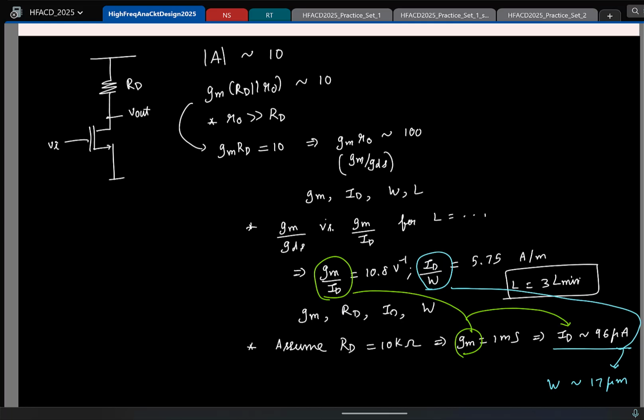Like even the question from the previous example, where we plotted gm/ID versus ID by W. In the simulation, won't we already know the width of the transistor? Yeah, but you are not saving the width finally. You are just saving the ratio ID by W. The idea is to generate width-independent parameters. So in that example, we are not essentially trying to find anything. We are just seeing the variation.